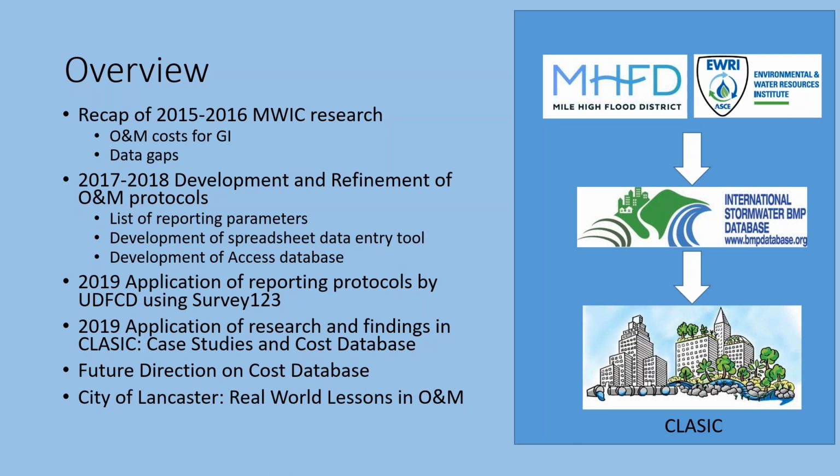From there, we moved to a subsequent phase of the project to actually develop and refine some O&M reporting protocols for all types of BMPs, not just green infrastructure, and developed a list of reporting parameters and some data entry spreadsheets in Excel, and have populated an initial cost database in Microsoft Access. We'll spend some time talking about those reporting protocols today.